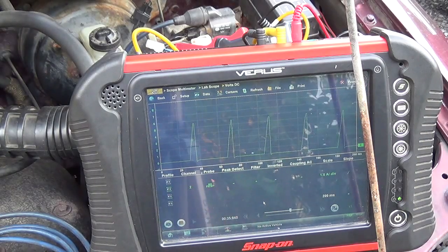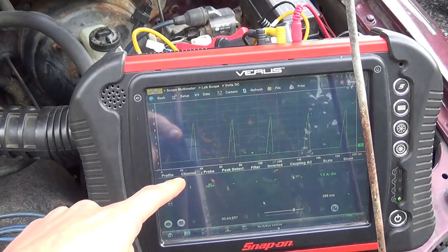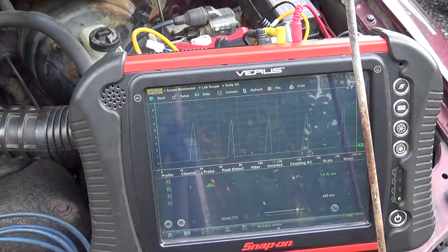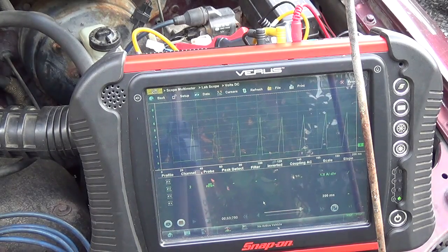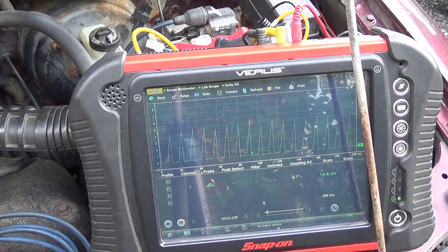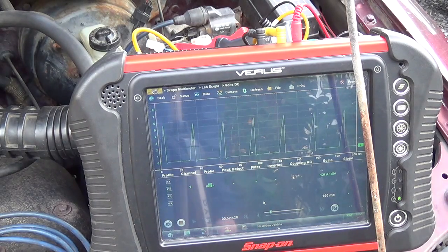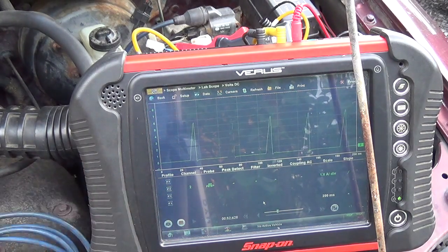So another thing we have to keep in mind is this is at idle. If we increase the RPMs, obviously the coil is going to fire more often, and we're going to have greater power consumption. That's the ICM. So if I rev it up, see how the peaks get closer together? So we'll do our calculation for 1,000 RPM, and to get the power consumption for 3,000 RPM, just multiply by 3. Really simple.